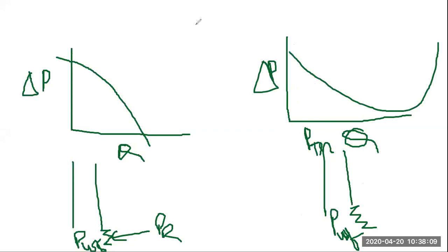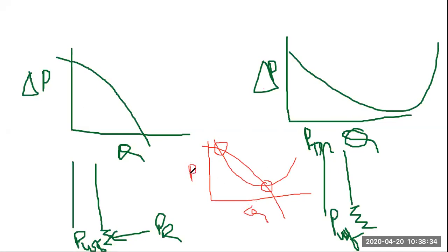What we do is we make a graph where we interpolate both of these graphs. So if I have this one and if I have this one, I check the places where both of these graphs are meeting. So this is flow rate and this is pressure. So I get that point where both of these graphs are meeting, this point or this point. So these points I need to find out. What is this point? This point is some flow, maybe Q0 we can take, and this pressure we may take as P0.